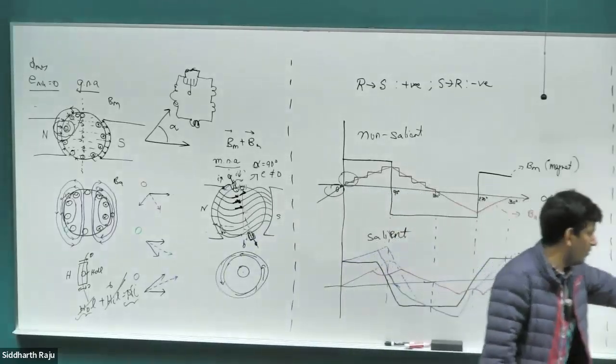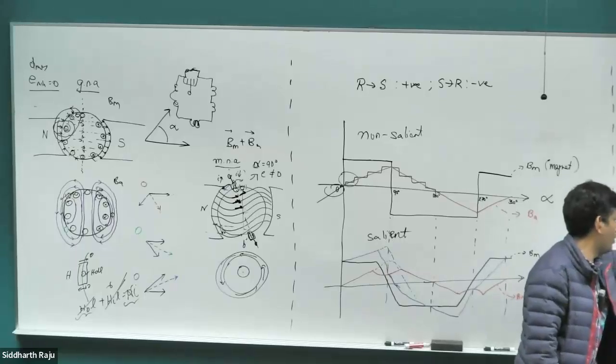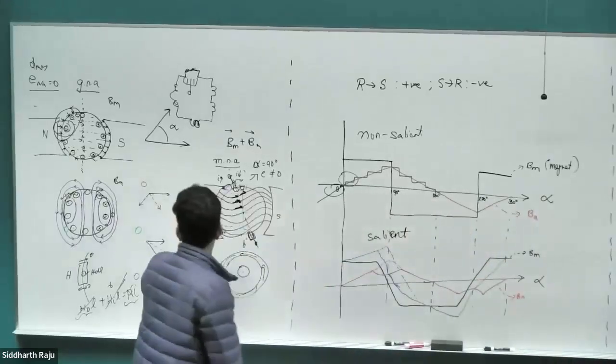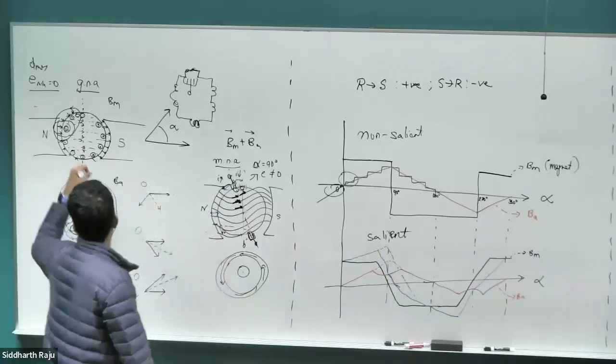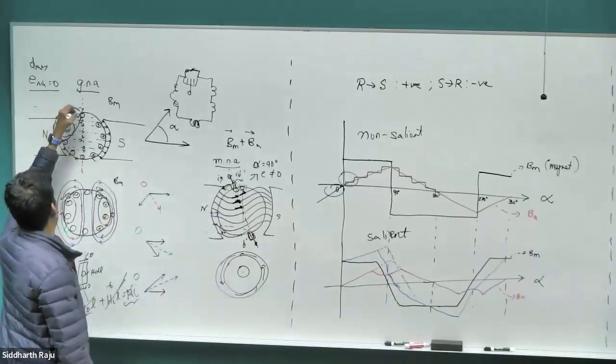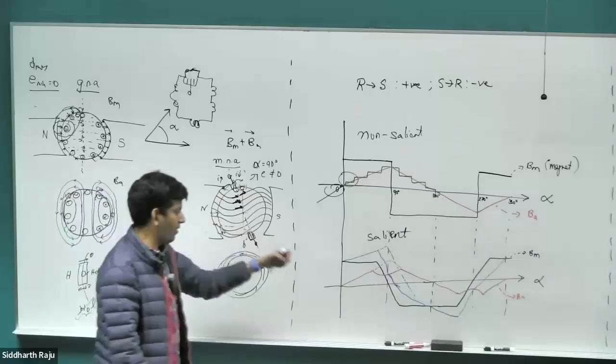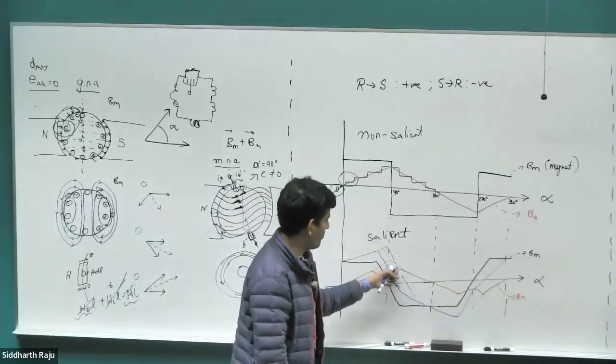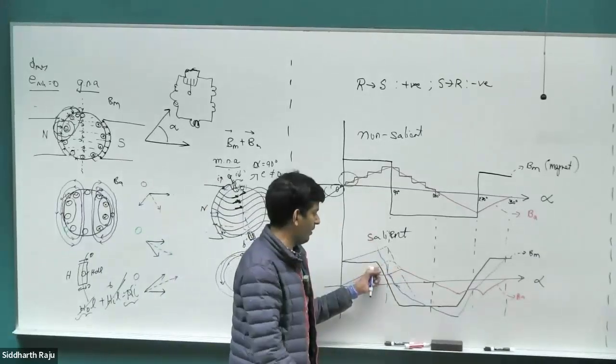Previously the Lg was just the distance between the magnet and the rotor. Lg was just this distance. Now, if you look at this, Lg is significantly larger. And just by making this change, we have reduced the effect of the magnetic field at the 90-degree angle due to the current carrying conductor.